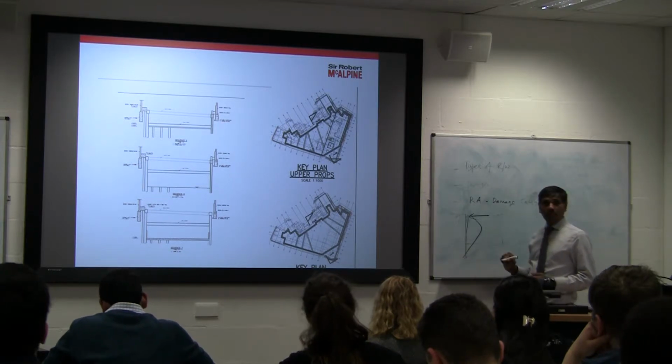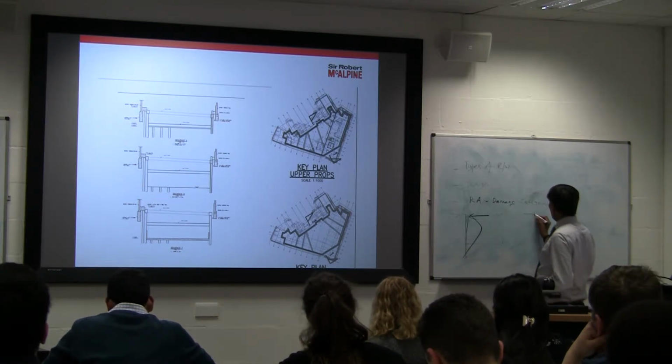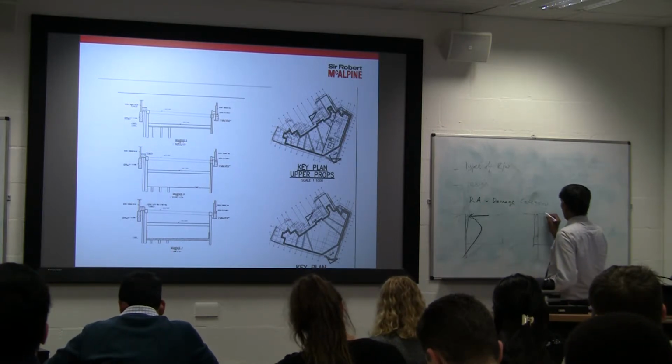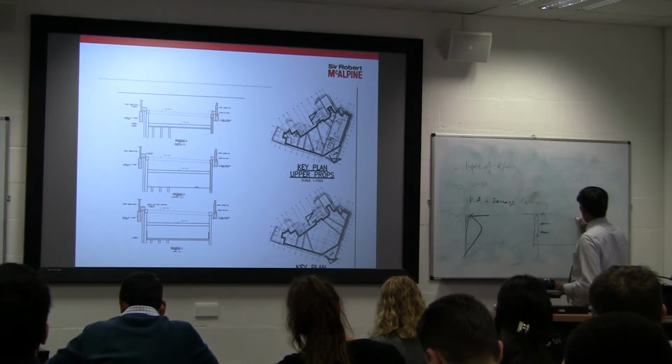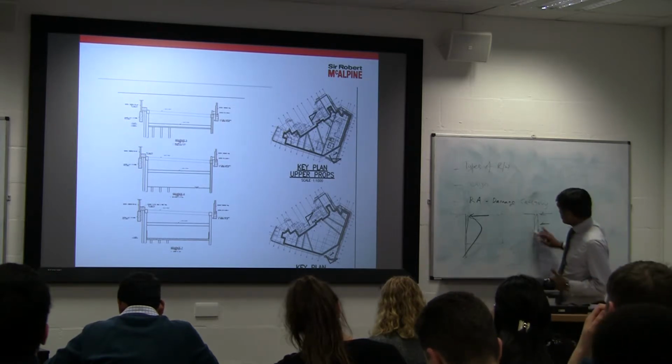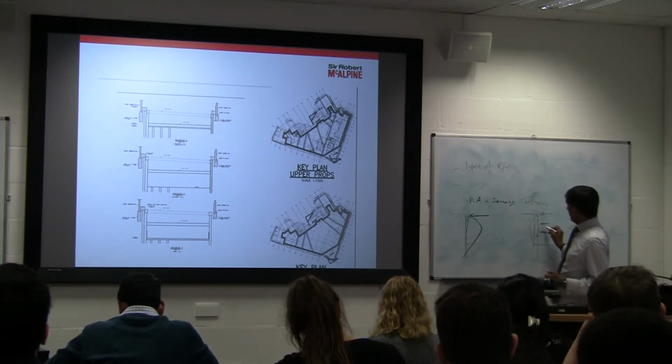So the bending moment is very high. Whereas if you put a multi-prop system, you've got a continuous system. So you've got a prop there, you've got a prop there, you've got a prop there. So you can see the bending moment diagram comes like that. So it's reduced. Yeah, it's like a continuous beam for all the loading that is applied.